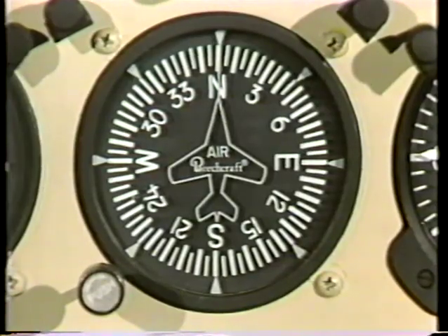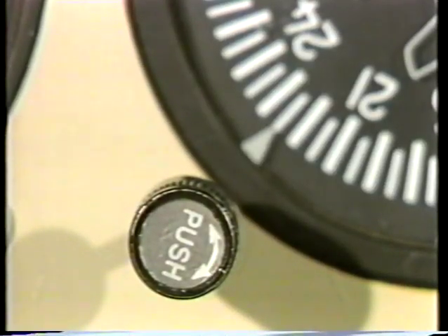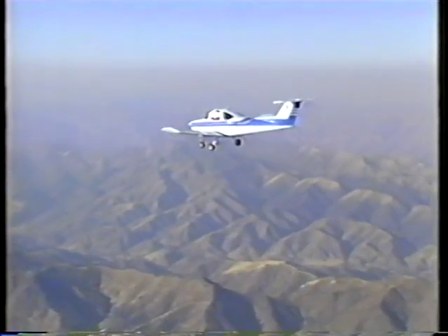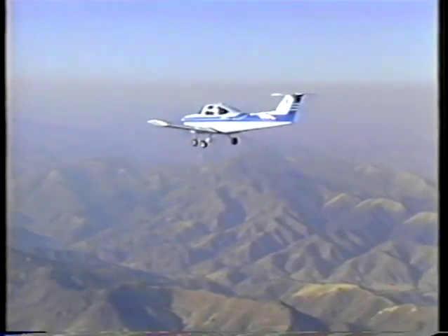Consequently, the azimuth card will drift from its correct setting during flight. This gyro drift requires the pilot to reset the heading indicator to a reliable source of heading information, such as the magnetic compass. This is done using the small knob on the left. This knob is attached to the azimuth and turns the card in either direction. It is important to check the indications frequently and reset the heading indicator to align it with the magnetic compass when necessary.